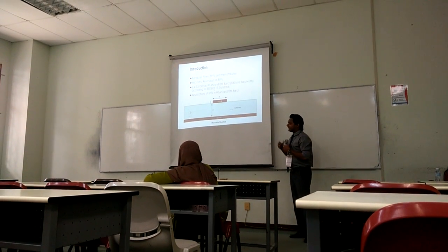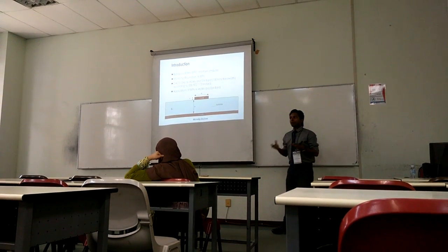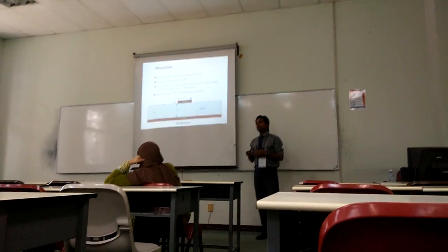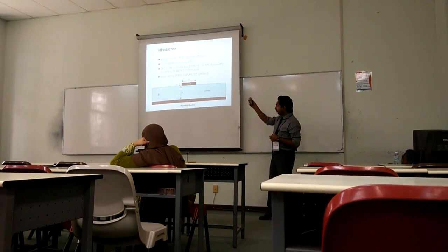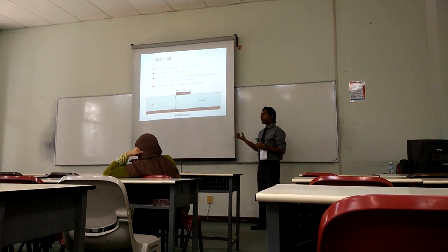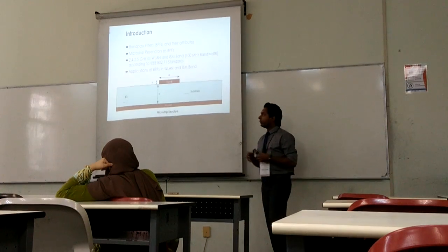By the way, for designing higher frequency filters, we use the microstrip technique. Why? Because lumped elements are not suitable and they have self-resonance frequency in the high frequency band. That's why we don't use them. We use the microstrip techniques because they are low profile, easy to fabricate, with distributed elements. That's why we use microstrip.